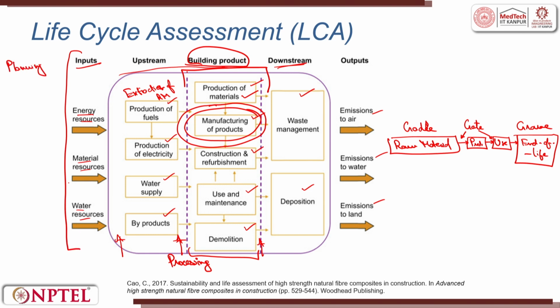I will call it planning, or I will call it the design that you do. So design for manufacturing. Design for manufacturing is known as DFM. That is, if you are designing a product, if I am designing this stylus, if I am designing this mouse, it has to be designed in a way so that it could be manufactured. The shape could be properly developed through the process that we are using.